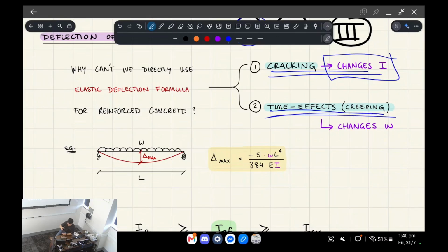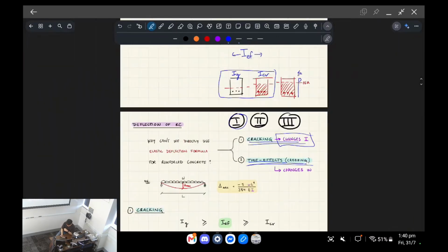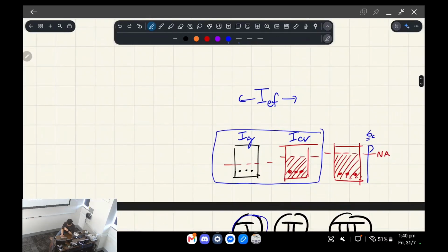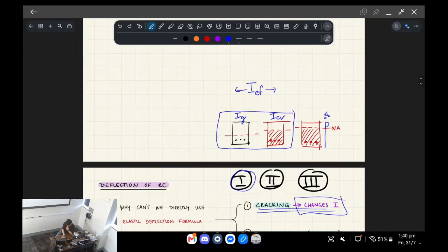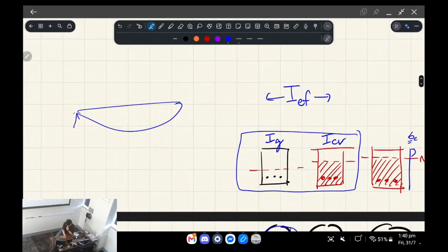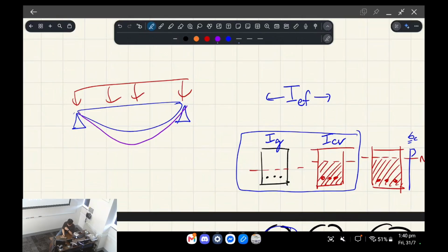It basically will, as you load it, right? So that's a beam. And you apply a constant load and you don't move it over a long period of time, let's say 10 years, it will actually sag more than the short-term loading. Okay, so if there's a beam and you put a bunch of bricks on it over 10 years, and you don't touch those bricks, it still will sag more.